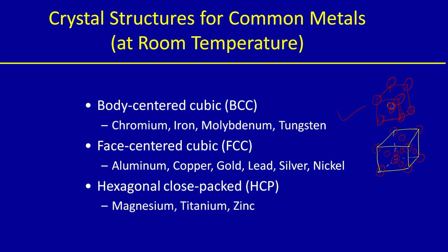So, there are 6 face centers, that is why there are 6 atoms in the face centers, and there are 8 corners. That is why it is the face centered cubic unit cell. And in this case the effective number of atoms is 4. Why is it 4? Because each corner atom is giving 1/8,